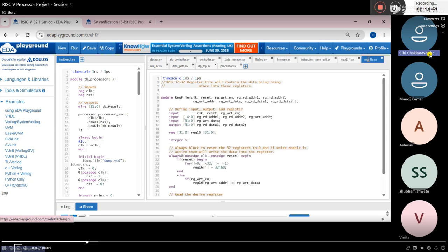And there is the reg file. As I told you before, why do we need the reg file? Because of the ALU operation. You must be strong in one thing: in order to perform ALU operations, we load the data from the data memory to registers, and using those register values we perform the ALU operation, or we pass the input values immediately. Other than that, we do not perform the ALU operation using the data memory directly.